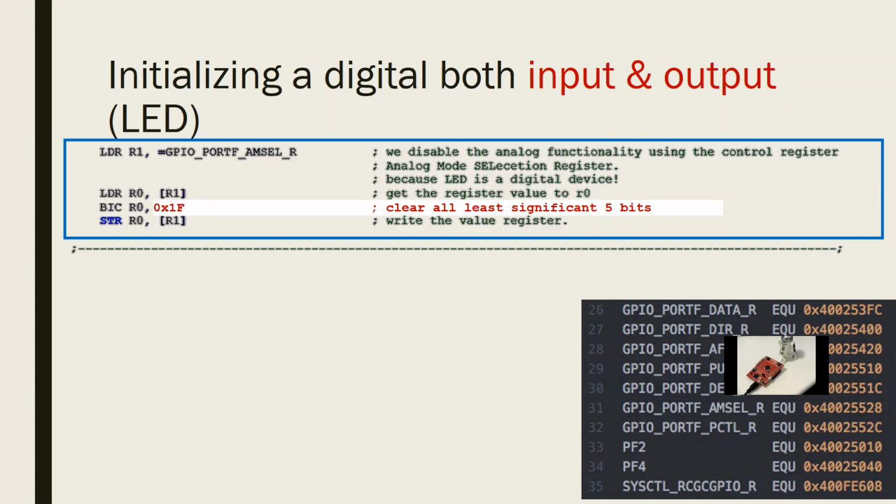That's a risk for your card because your card's architecture has some current limits that it can bear. Otherwise, it will burn. This card has some protection circuitry inside. If you select the analog mode selection register, it will activate those protection circuitries so that the analog device which you connect to will not harm the card.